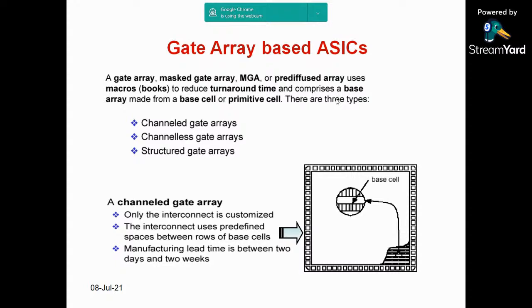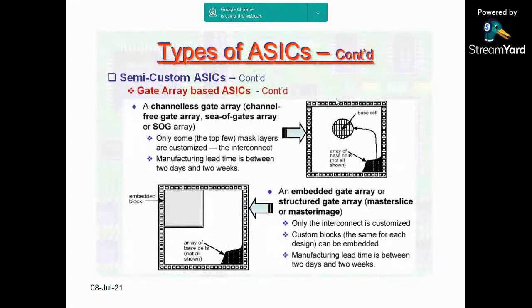The only difference is between the standard cell approach and the gate array. Standard cell uses only pre-tested and pre-characterized cells available in the library, whereas a gate array is almost manufactured, fabricated, and left bare. They won't do packaging. You need to say where the interconnections are, and the fabrication people will fabricate it and give it to you.